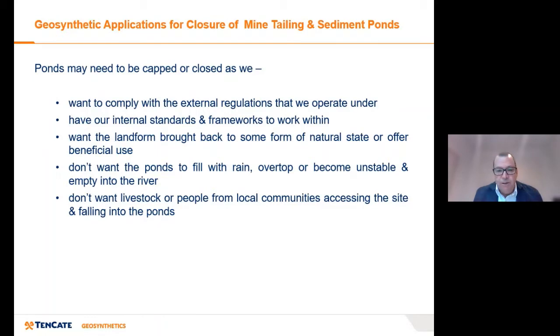It might have a safety or environmental aspect, such as after you leave site, you don't want people wandering in or livestock wandering in and falling in the pond, or the pond itself overtopping and emptying into the river. So there's a number of reasons that you would actually close the pond down.